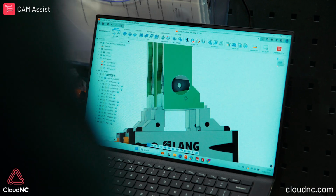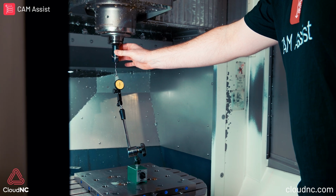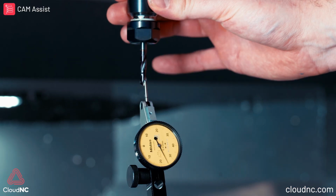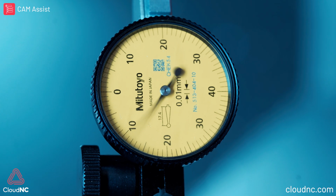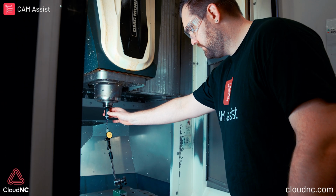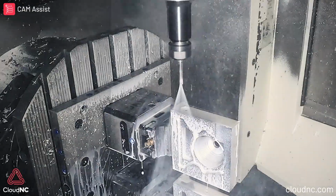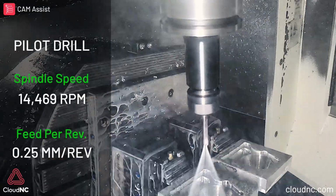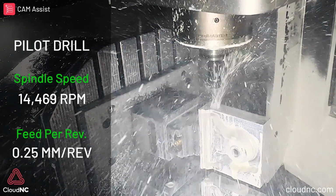Now let's talk about the drilling strategy itself. It is essential that the stubby pilot drill has minimal runout and should be checked with a dial test indicator, as this drill is responsible for drilling the pilot hole in an accurate position to be used as a guide for the much longer drill. The pilot hole is drilled to a depth of up to 2 times its diameter. Spindle speed is 14,469 RPM, with a feed per revolution of 0.25 millimeters.